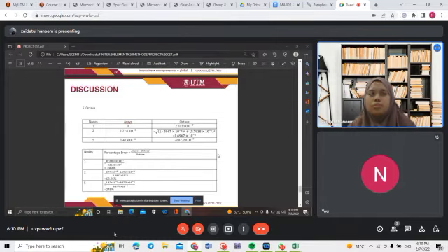So we get a huge error because there might be an error when we combine the global matrices, because we combine them by manual calculation. So there might be some error when we put the k based on rows and columns.